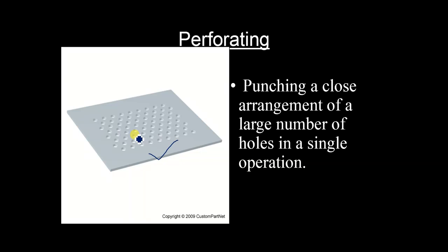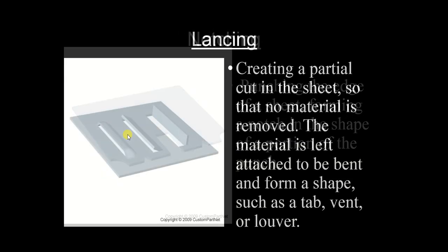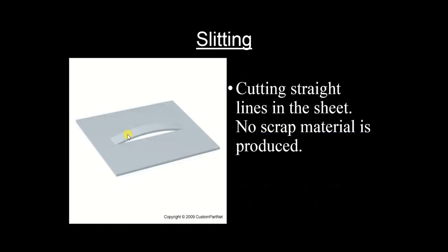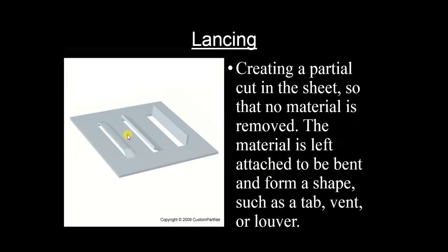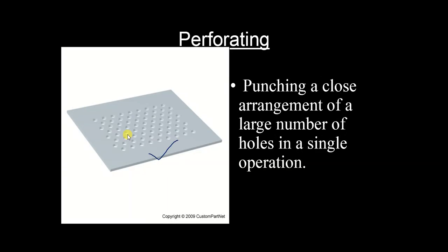If you look at certain electronic equipment such as CPU enclosures or microwave enclosures, maybe you will find perforation on the exterior enclosure, or you will find lancing or slitting. Most commonly I have found lancing in the water cooler, and perforating in CPU enclosures, and also in any enclosures where there is heat which we want to eliminate outside.